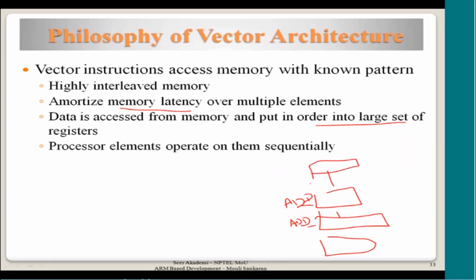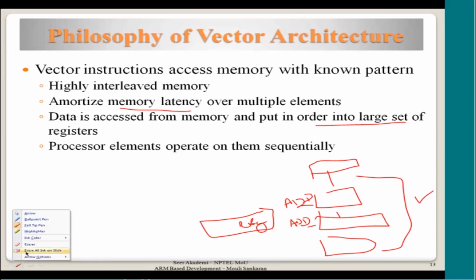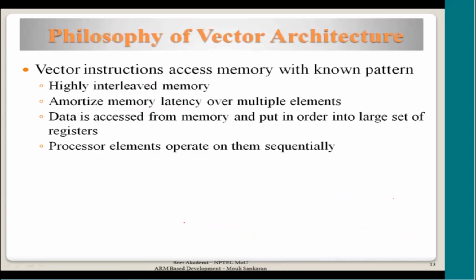So a vector processor will have more registers in the system. It also has more processing elements, the multiplication or arithmetic units, as well as more registers, so that the operands can be kept in them and accessed by multiple processing elements simultaneously. Then they operate on the elements one by one, and the processor writes the results back into memory.